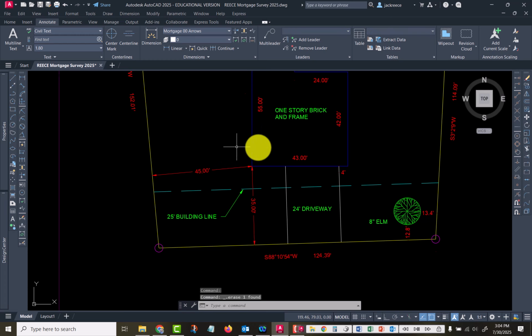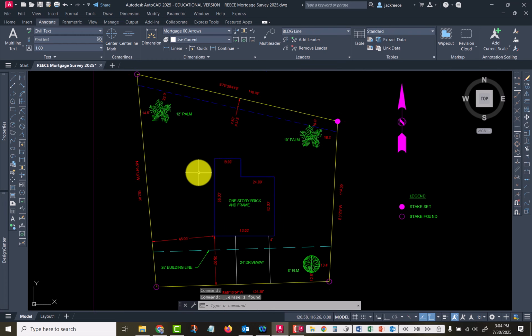Now, a good way to do these things, you could do it on the house. You can do it on the property lines, is if you go align dimension, and in your options is specify first extension line origin or select the object.